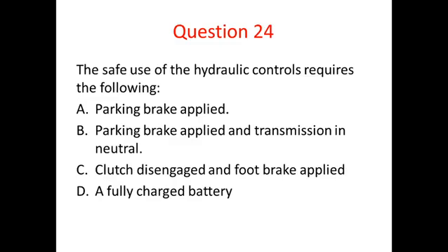24. The safe use of the hydraulic controls requires the following. So what would you need to do before lifting the load? You need to park safely, so parking brake applied, and the transmission in neutral. You want to make sure you're in neutral so you don't accidentally press the accelerator, sorry, and cause the truck to move forwards via the forward momentum of the vehicle overpowering the handbrake.